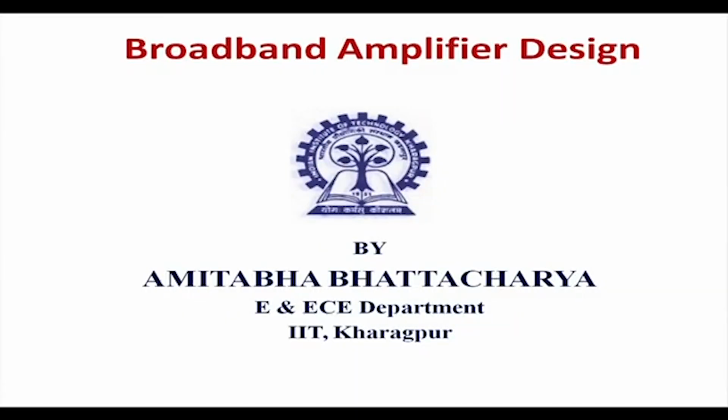Welcome to today's lecture. Today we are continuing our amplifier design lectures. So, today we will see another class of amplifier which are broadband. We have seen that if we do conjugate matching, that match and also S parameters of any transistor are true for any particular frequency, but many times we know that since our baseband signal is a band of signal, it is not a spot frequency.